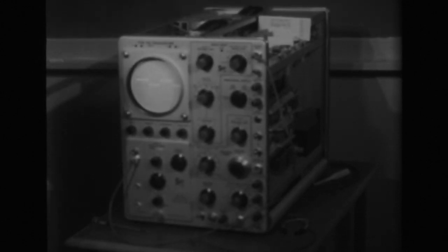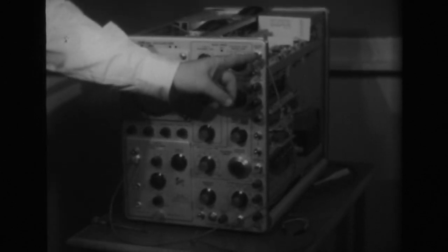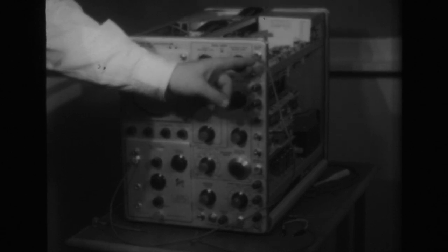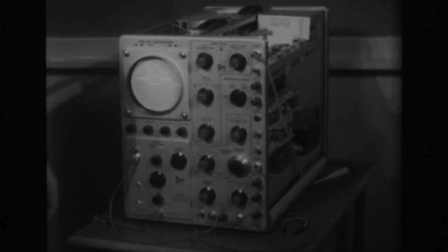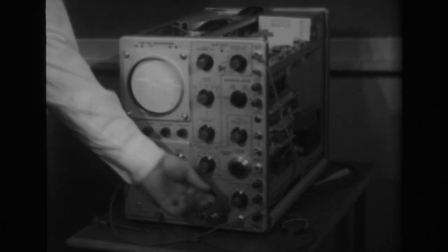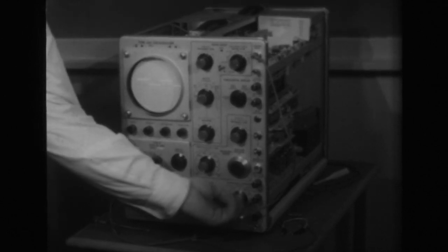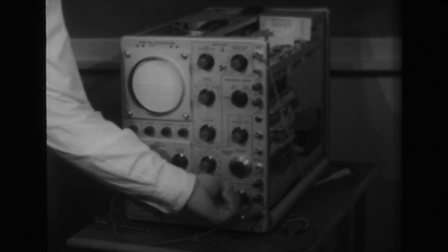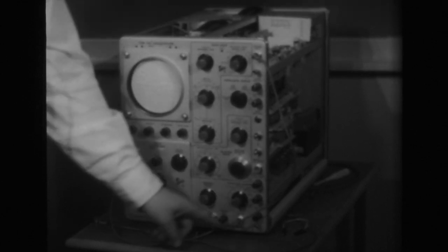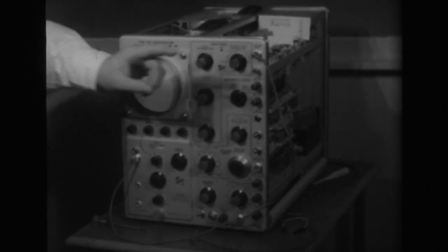to verify that the sweep will not trigger successfully on a 100 millivolts peak-to-peak square wave fed in externally. We have just seen that it will trigger successfully on a 200 millivolts peak-to-peak square wave fed in. So now let's change the calibrator square wave generator from volts to millivolts and the output control to 100 millivolts. We now have 100 millivolts peak-to-peak amplitude applied to the trigger system.